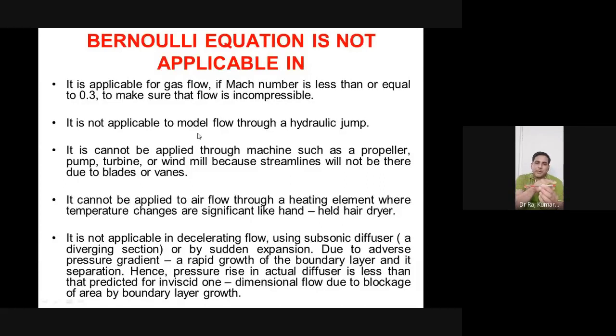You can apply your Bernoulli from here to here, but not across this cap because this is a pump. Here you don't have a streamlined flow pattern. So you will always skip the pump. You can apply it on a straight pipeline, but not on the pumps.